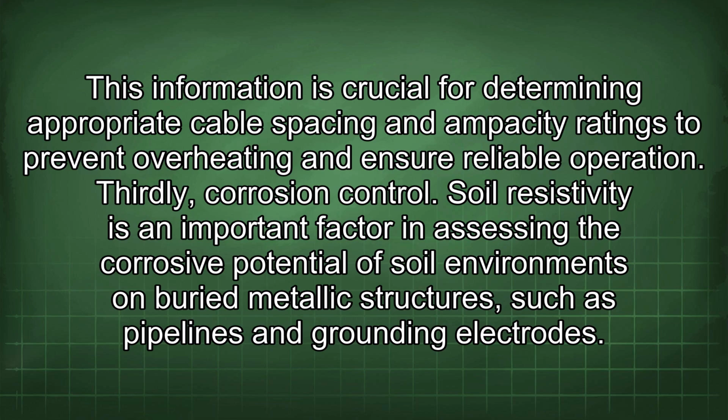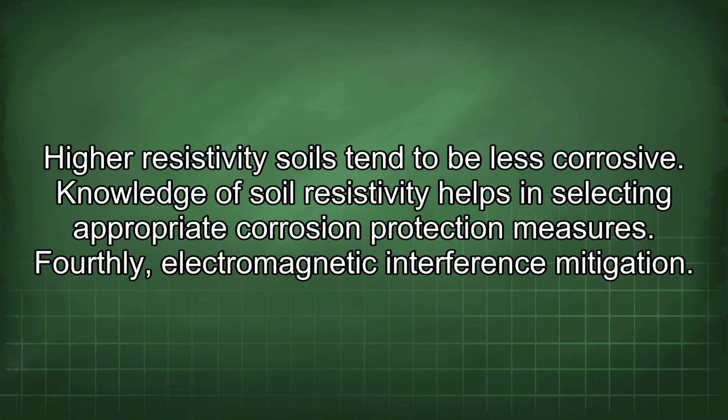Thirdly, corrosion control. Soil resistivity is an important factor in assessing the corrosive potential of soil environments on buried metallic structures such as pipelines and grounding electrodes. Higher resistivity soils tend to be less corrosive. Knowledge of soil resistivity helps in selecting appropriate corrosion protection measures.